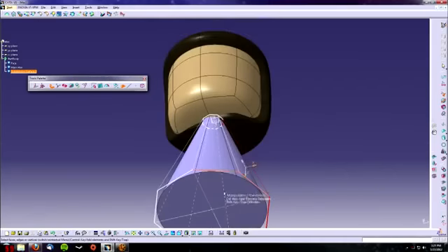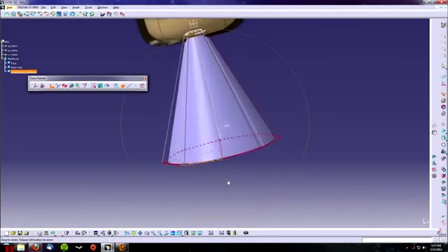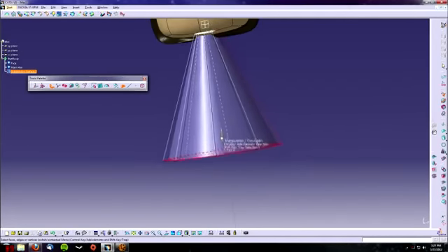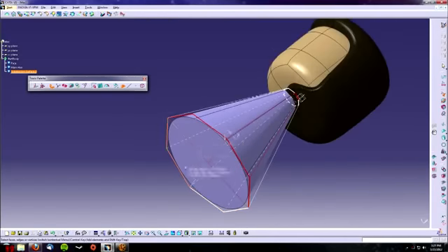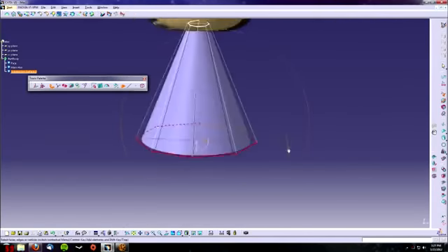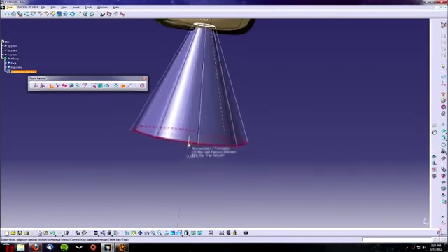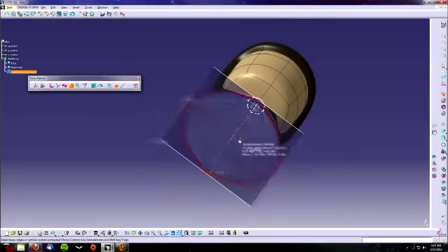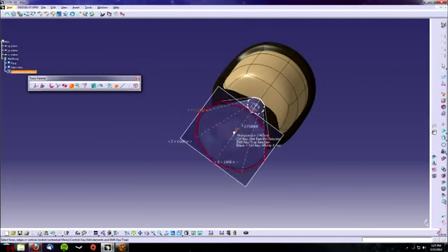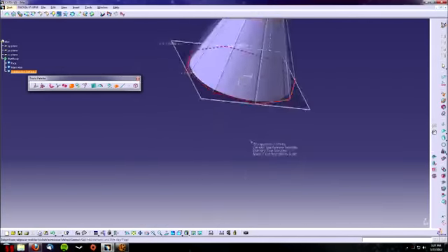Once you're done with that, go ahead and do the same thing to the bottom. Select the bottom four panels, well actually bottom surface. You're going to use the affinity command and the translation command to make it smaller and to move the bottom of what will basically be his body closer to his head, similar to how you see in this picture where his t-shirt is. This will be the basic framework for when we make his t-shirt as well.